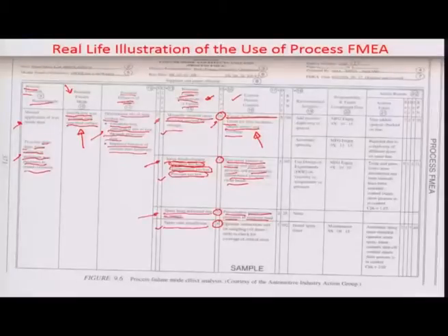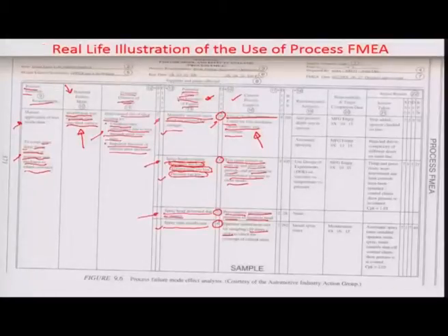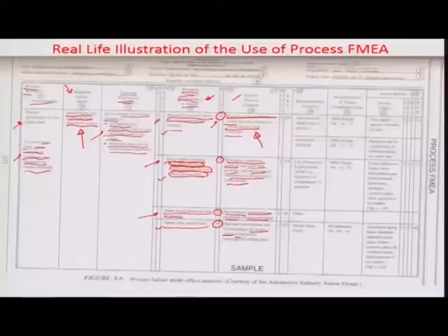Also, for the spray time insufficient, probably there is a 10 doors per shift checkpoint done by a supervisor, to ensure that if some operator is untrained and is not doing the job properly and the spray time is insufficient, there is a check on whether the spray time is insufficient, because of which there is a coverage issue of the wax on the door inner.